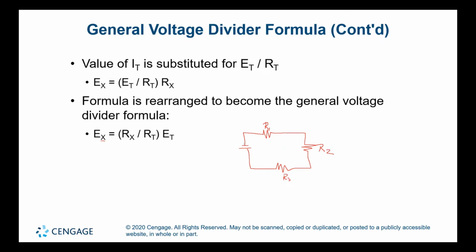And of course here, right at the source, when I measure with an ohm meter, if I wanna be able to determine my RT, I'm gonna have to measure between these 2 points, between here and here. Let's call these 2 points A and B. So if I want to measure my total ohms, it's going to be measured between A and B. And because it's measured between A and B, right here also between those 2 points, we find RT.